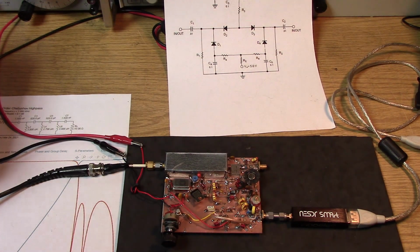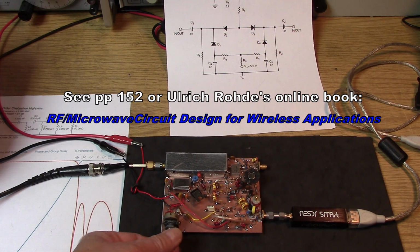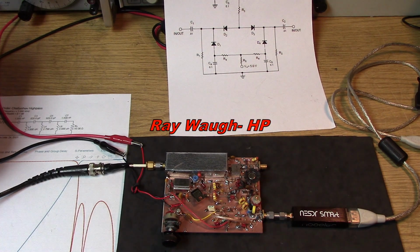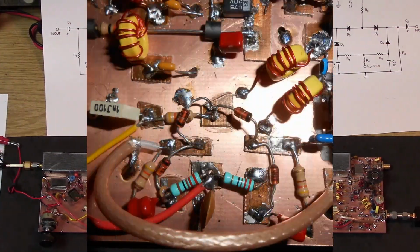So I promised that I would develop a simple attenuator that had a control so we could change the gain. And I found this wonderful circuit, and you have to give credit to a Hewlett-Packard engineer that developed this circuit, but I really didn't know what resistor values to use, so I just took a guess at some of them. I used ordinary 1N4148, 1N914 diodes rather than pin diodes, and it's working wonderfully.